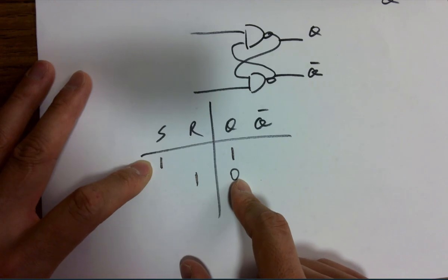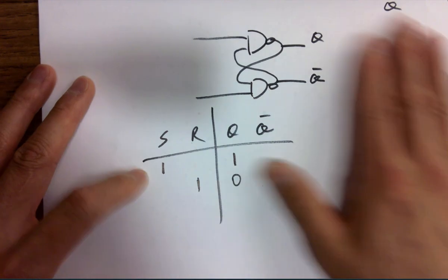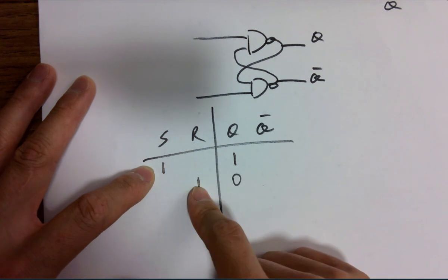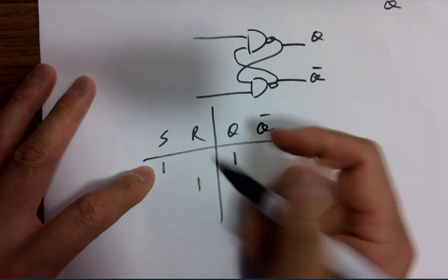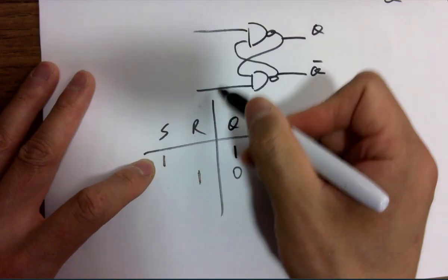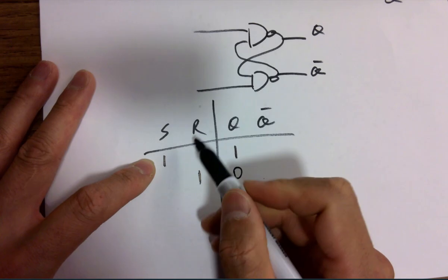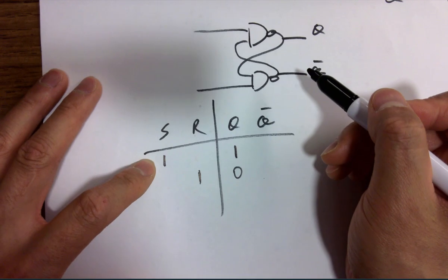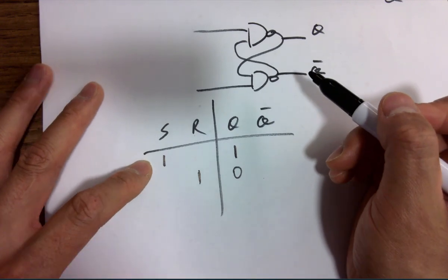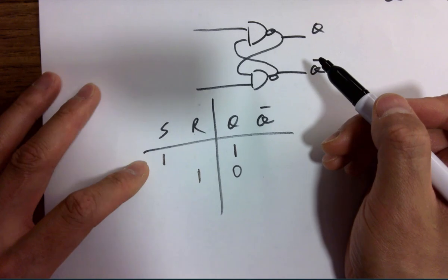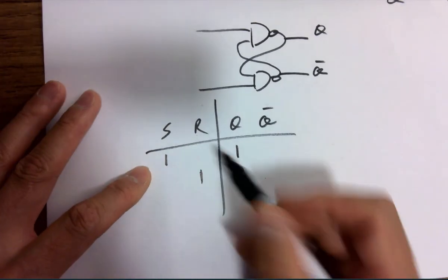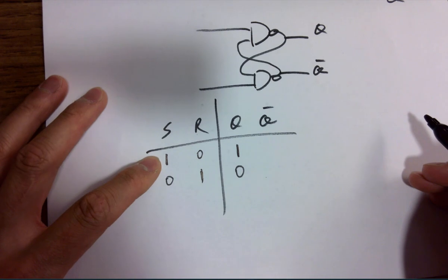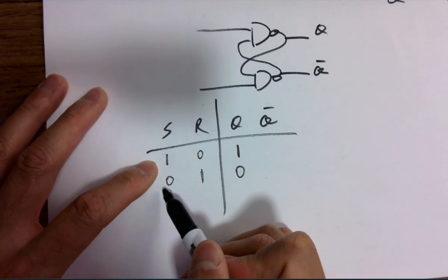Knowing how this works will never become an issue since you understand it right now. It's called S and R because you turn this on, you set it; you turn this on, you reset it. Now, I will show you why, but we never set and reset this latch at the same time, because we just want to set or reset, not both. So don't abuse it. We set, we don't reset. We reset, we don't set. Make sense?